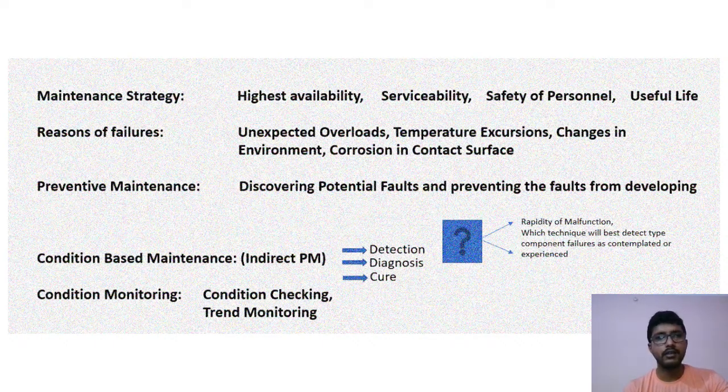And what are the conditions or the parameters responsible? The ppm in oil, the dissolved gases, moisture, and all those things. So we need to work upon that. If they are above a certain threshold value, we need to take corrective steps. We'll run the circulating conditioning machine or the filtration unit, or some such steps we take.